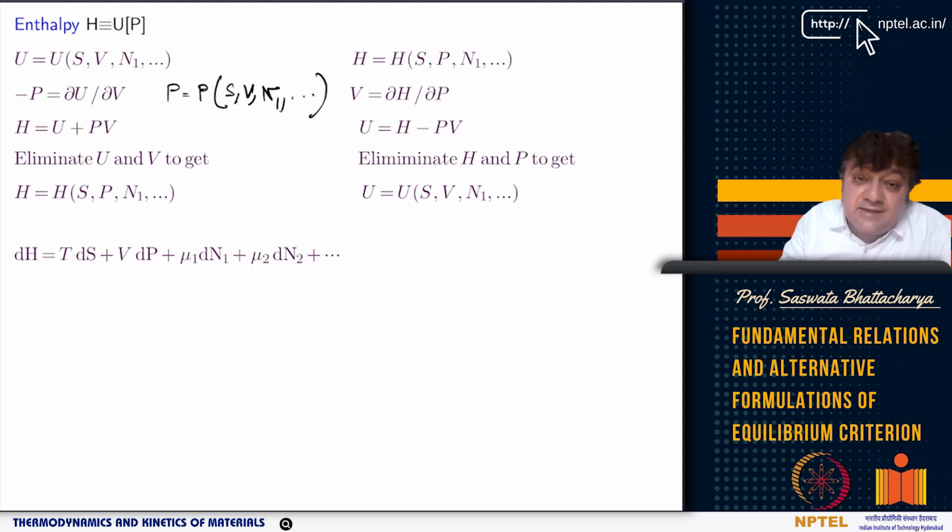However, now if we think that we have a pressure reservoir, basically a pressure reservoir is such that there is a wall between the system and the reservoir, and the wall is flexible, but whatever be the change in volume, there is no change in pressure, right? The pressure in the reservoir is kept constant, right? Because the change in volume is so infinitesimal when you consider this infinite reservoir, then basically what we are saying is the pressure inside the reservoir remains unchanged. So obviously the system will assume the pressure of the reservoir because of mechanical equilibrium, right?